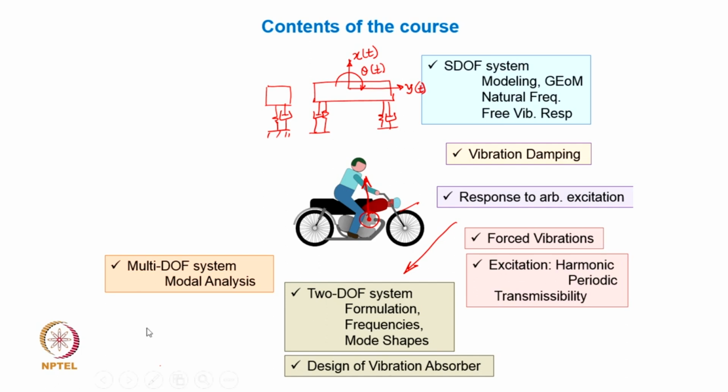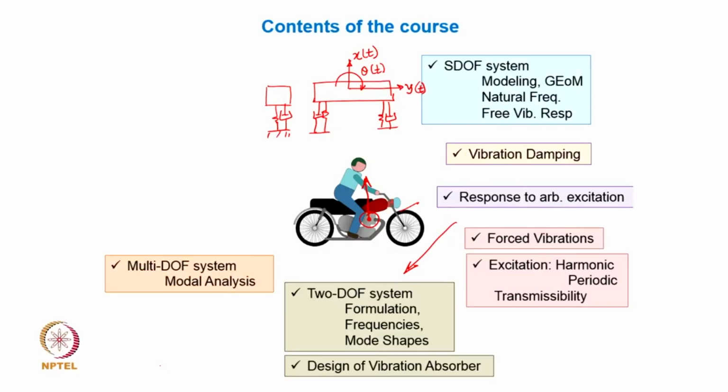how to formulate the governing equation of motion for multiple degrees, which means that going in far beyond 2 or 3 or 4 of them. In this particular topic, when the degrees of freedom substantially multiplies and increases significantly, the efficiency of solution process is important. Typical discretized numerical models such as done through the finite element approach will have several thousands of or several tens of thousands of degrees of freedom, and then solving them becomes a challenge.